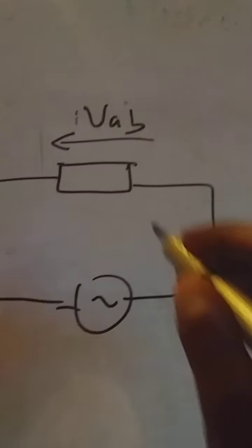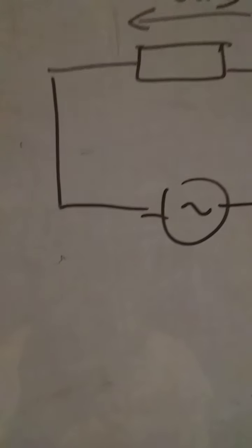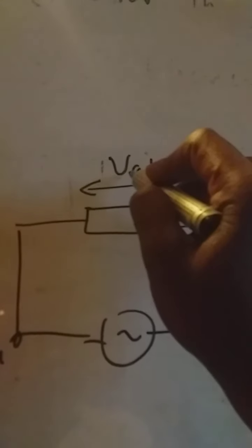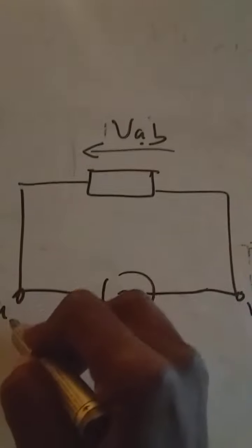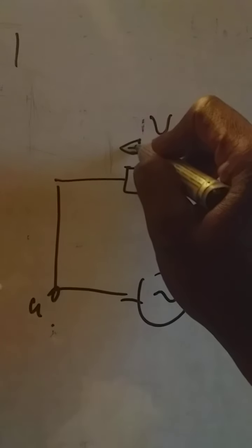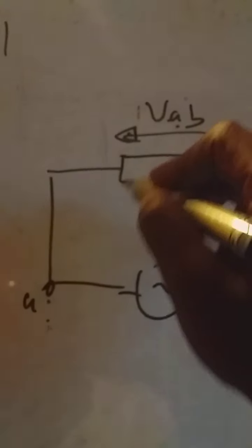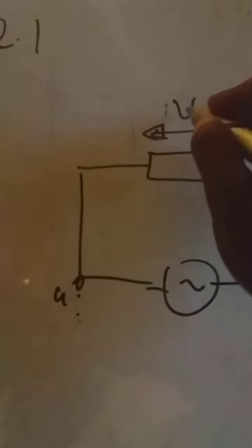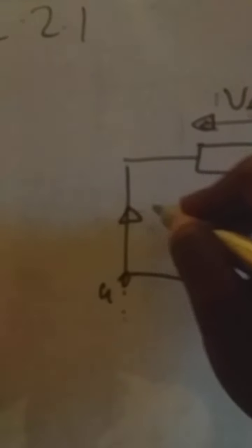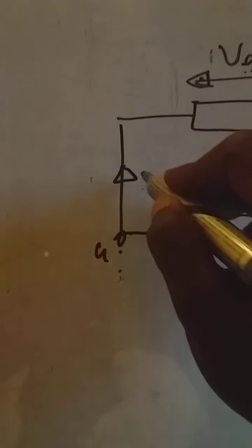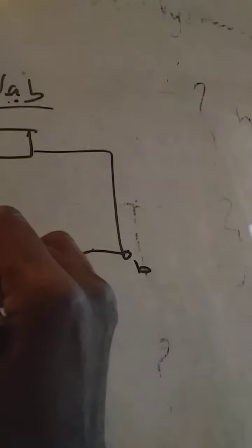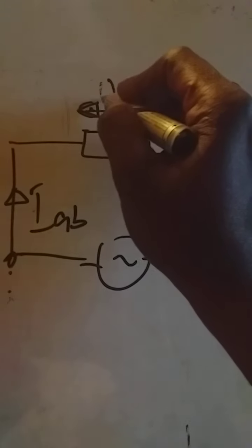The voltage VAB only tells you A is at a higher potential, and that is why the arrow points towards A. Where the arrow points to tells you that is where the potential is higher. So if the higher potential is A, that means automatically current will flow from IA down to B. So VAB is the voltage across.